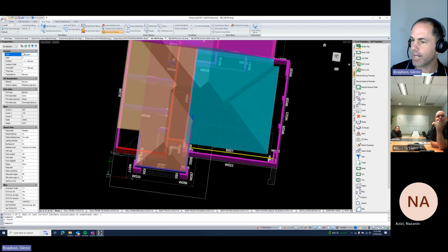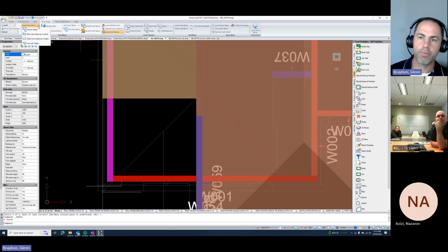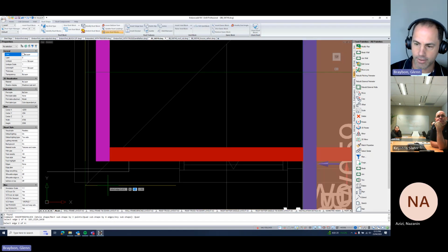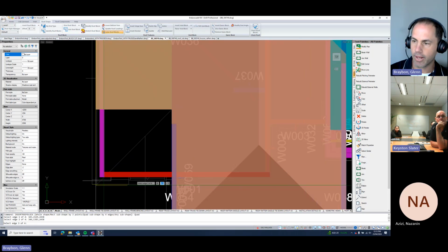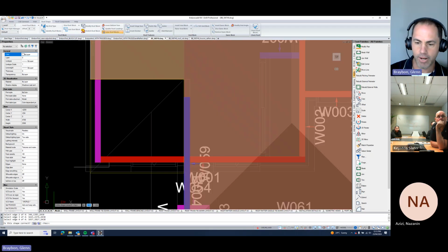So we've got those blocks there, and then I would insert a roof block quad sub shape by 4 edges. You guys would be aware of that. We're obviously going to use that edge. I did build that construction line in, just coming off that hip, bisecting that outside of that pitching perimeter with that hip. Select there and there. We're going to select that edge, and we're going to select that edge. Is this shape correct? Yes.